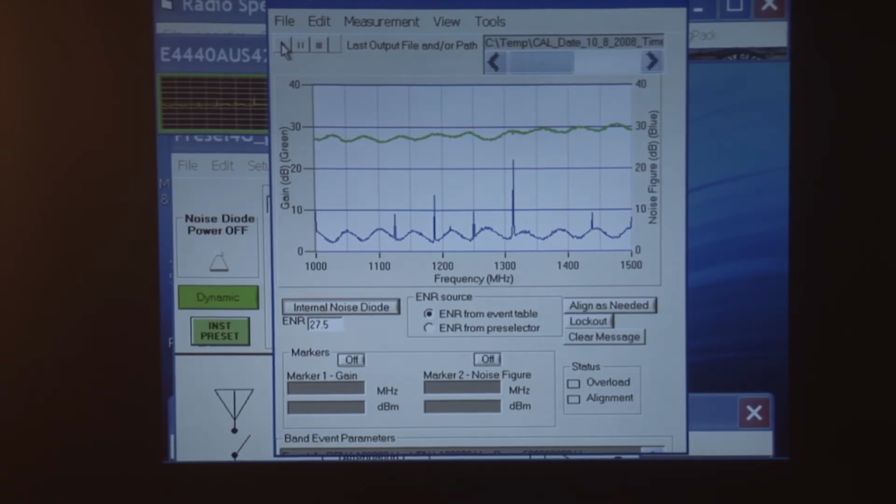But this gain is going to cost us dearly when we're doing measurements, because it's eating up, and we've talked about this in some earlier talks, but I want to bring this home today, it's eating up the dynamic range in our measurement system. In other words, a fairly weak signal is actually going to overload our measurement system. That's a problem. Now, do we need all that gain?